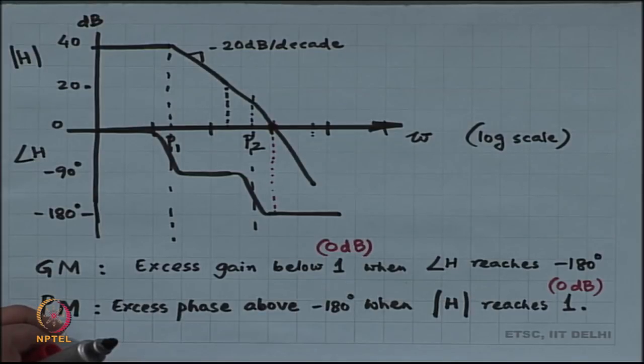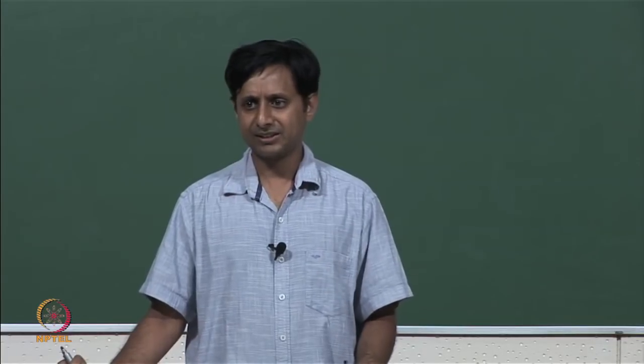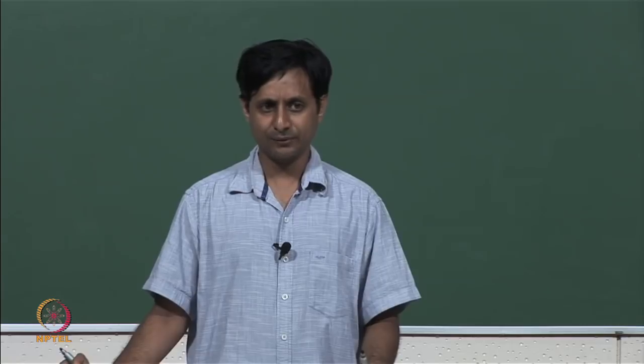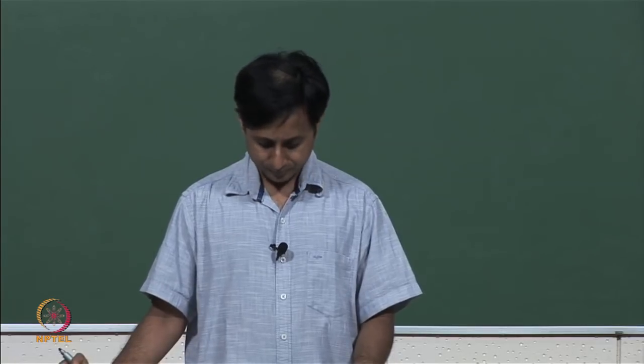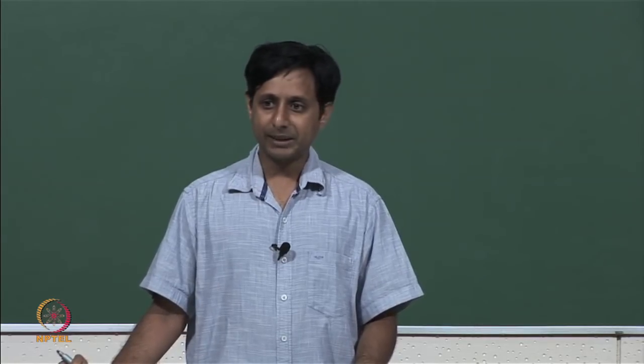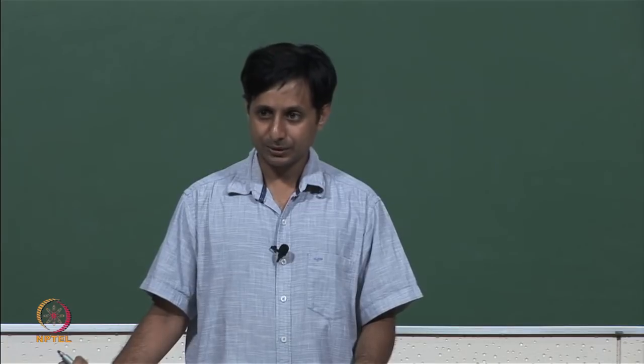So, either there is no phase margin or slight amount of phase margin, something of that order, right, 0 or close to 0 degrees of phase margin. So, it might be in fact hard to measure.